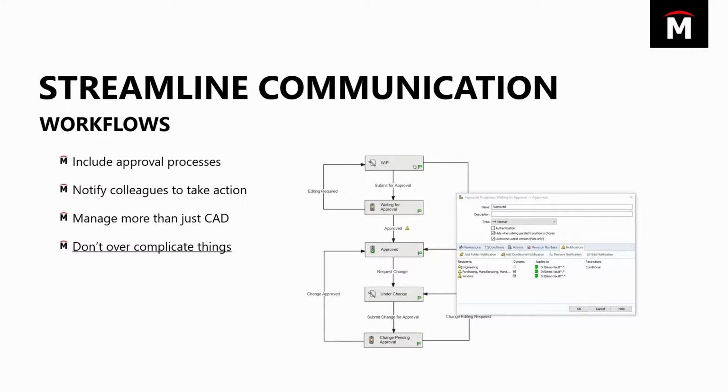And keep in mind that you can manage more than just CAD. PDM's a great tool for SOLIDWORKS files, but it's a great tool for a lot of other files as well. You can manage different workflow processes for Excel files, Word documents, basically any file type that you would like to store in PDM. And then lastly, don't forget, don't overcomplicate things. Start off simple, work your way up, make sure that everything is really effective as is before you go and add additional states. It's a lot easier to scale up than it is to scale back down with workflows.